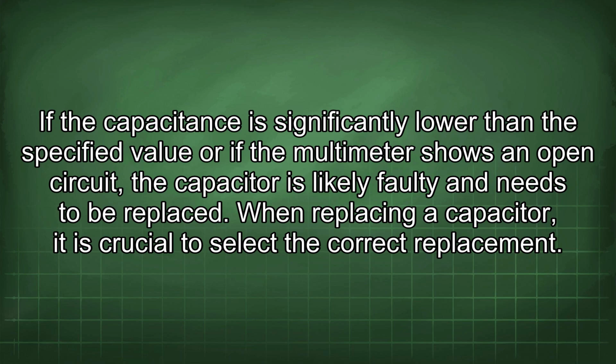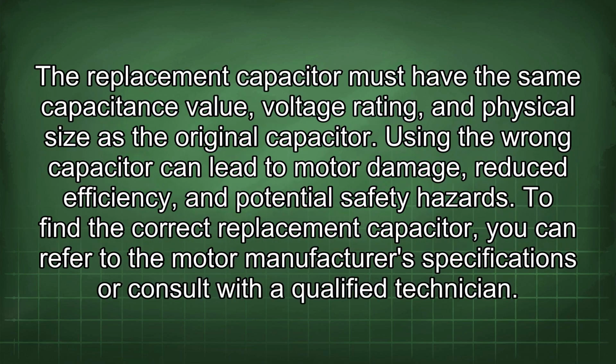When replacing a capacitor, it is crucial to select the correct replacement. The replacement capacitor must have the same capacitance value, voltage rating, and physical size as the original capacitor. Using the wrong capacitor can lead to motor damage, reduced efficiency, and potential safety hazards. To find the correct replacement capacitor, you can refer to the motor manufacturer's specifications or consult with a qualified technician.